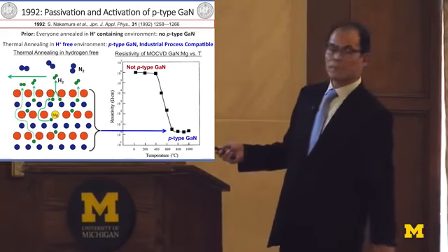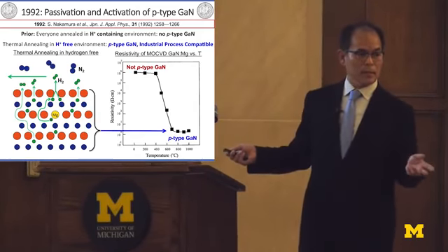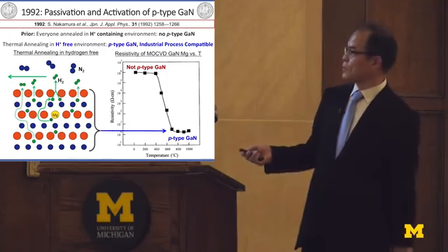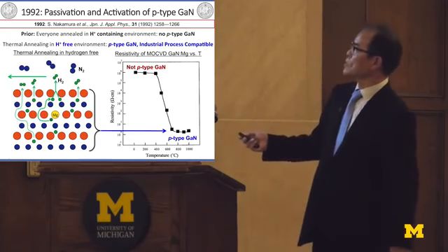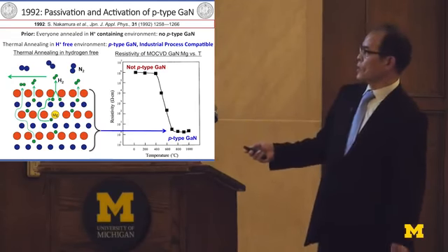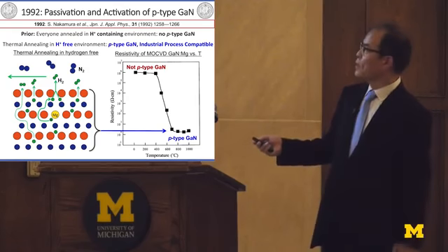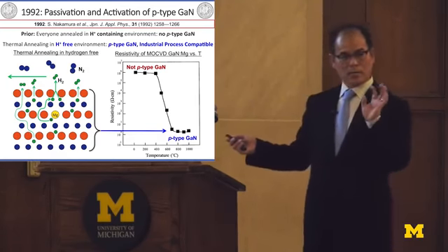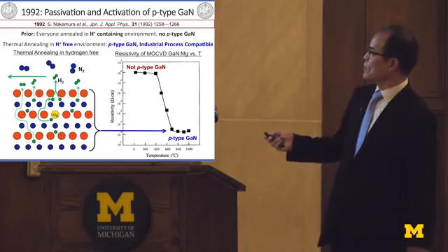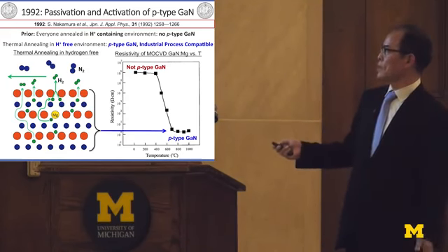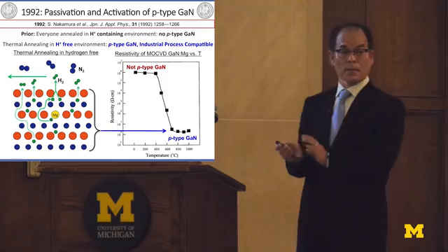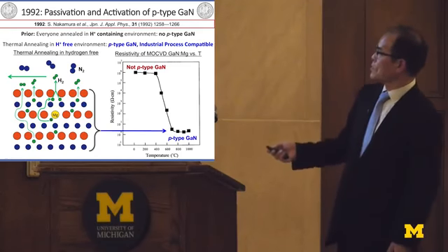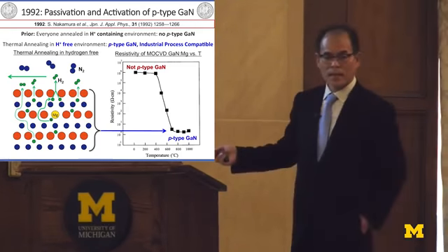The problem with P-type gallium nitride is that we always use magnesium to make it. Magnesium should act as an acceptor. But the resistivity always became semi-insulating when we doped magnesium. Professor Akasaki just accidentally irradiated the electron beam and got a low resistive P-type gallium nitride, but they couldn't understand the mechanism. But in our case, we just used thermal annealing.